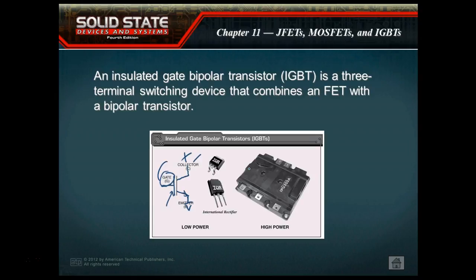And these guys here can handle extremely high powered loads. So here we have a real high input impedance on the gate, which means the devices that are controlling these things. These enhancement mode MOSFETs, their biggest advantage, of course, is ease of switching, acting like a switch. The biggest advantage of bipolar transistors is the amount of power they can handle, because when we saturate those guys, the actual junction goes down to less than a volt, right? You saturate an FET, you still have the resistance of the channel, of the semiconductor material. So that's the big advantage.